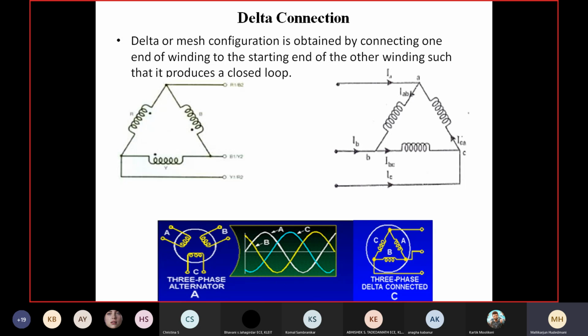For that, let us take this diagram like this way. I have three windings, winding 1, winding 2, winding 3 connected end to end such that a delta is created, and leads are brought out for the end connection. You may ask me, you have marked the current going in. What is wrong if I take the current outward? Of course you are right. Whether you are considering a three-phase load or a three-phase generator, the connection and relationship exist the same way. So no matter whether IA, IB, IC are entering A or leaving A, it doesn't make any difference. This is already written in many of the books, you can remember.